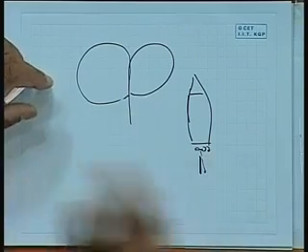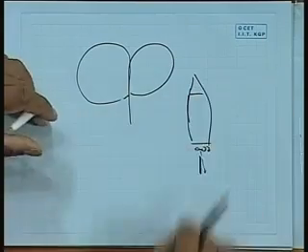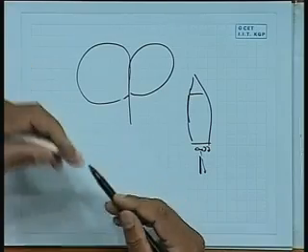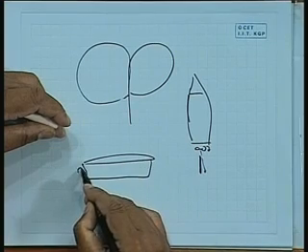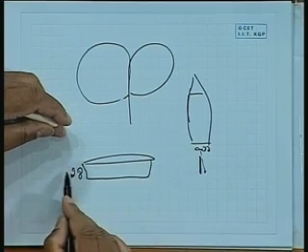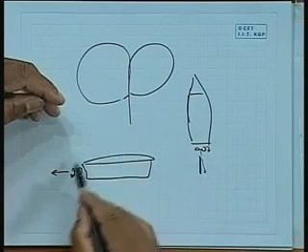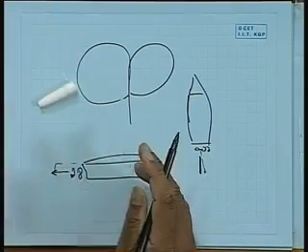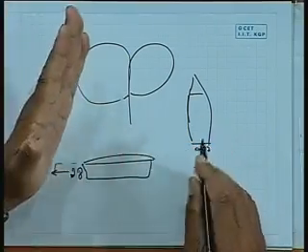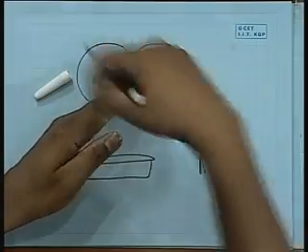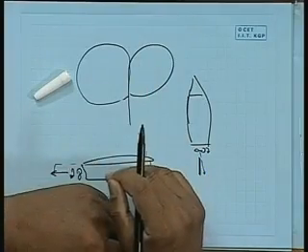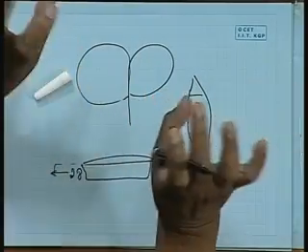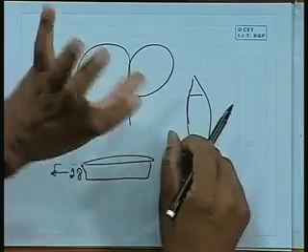See, propeller is rotating in one direction, so the flow is not symmetric exactly along the x-axis. How can it be symmetric? It is very difficult to draw a three-dimensional picture, but see, propeller is rotating here in this direction. So along this line, if you take a center plane, propeller is rotating one direction. So here the flow is not exactly along this line, it will be slightly on this side. Had there been two side propellers, then it would have got counterbalanced. But it is one side propeller, you see.